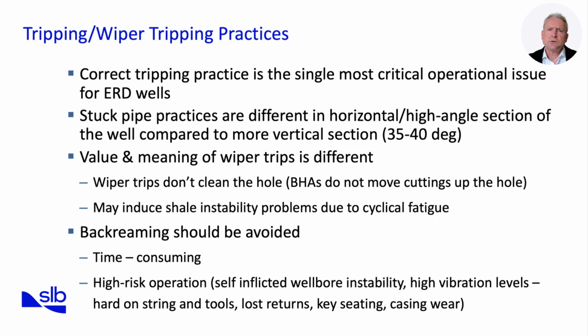Another practice to avoid is back reaming. While sometimes used to address tight spots, it is time-consuming and carries high risk. Back reaming can create self-inflicted wellbore instability, cause high vibration levels, accelerate casing wear, or even lead to lost returns. In summary, tripping in ERD wells must be deliberate, controlled, and minimized. Now, let's wrap up this submodule by reviewing the objectives and confirming what we've covered.